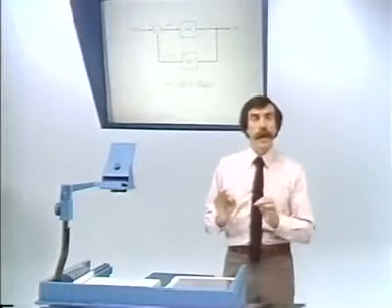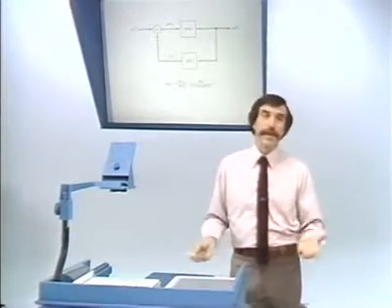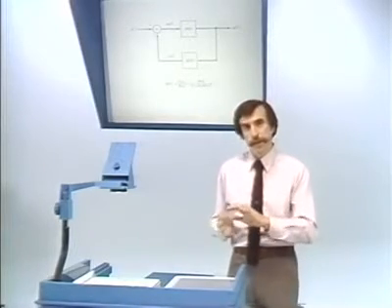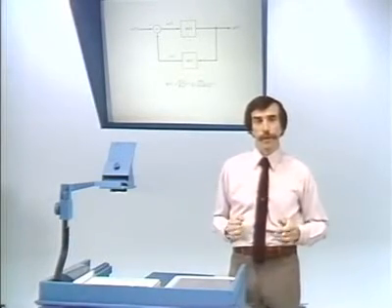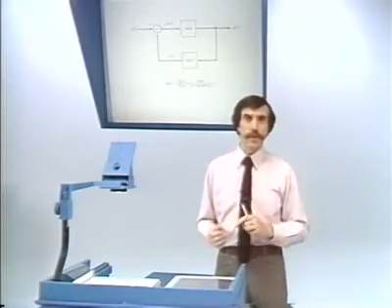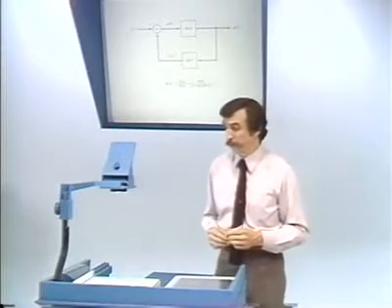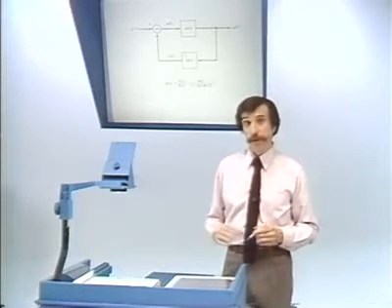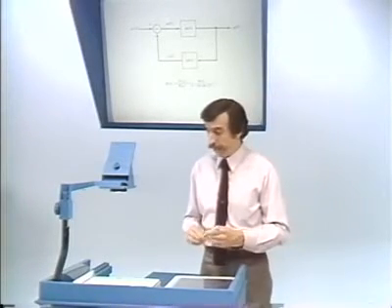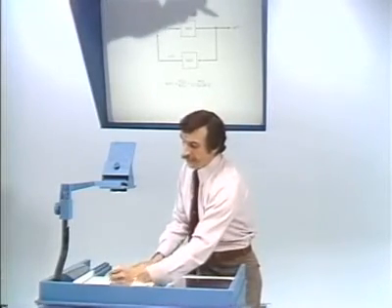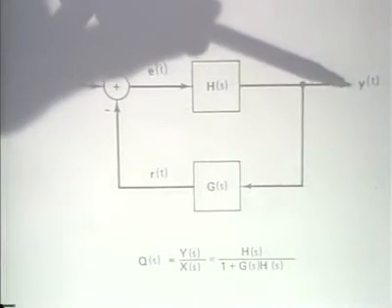Now, if we want to analyze the feedback system, we would do that essentially by writing the appropriate equations. And it's best done in generating the equivalent system function for the overall system. It's best done in the frequency or Laplace transform domain rather than in the time domain. And let me just indicate what the steps are that are involved. And there are a few steps of algebra that I'll leave in your hands. But basically, if we look at this feedback system, we can label, of course, since the output is y(t), we can label the Laplace transform of the output as Y(s).